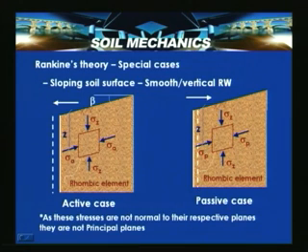Then at the point of plastic state of equilibrium, a rhombic element is shown here. So in this case, these stresses can no longer be called principal stresses because these surfaces are not horizontal, so they carry some shear stresses. But these particular stresses, this is sigma z at a depth z, measured along this z as shown here, and sigma a is the active earth pressure, and sigma z is the vertical stress here.